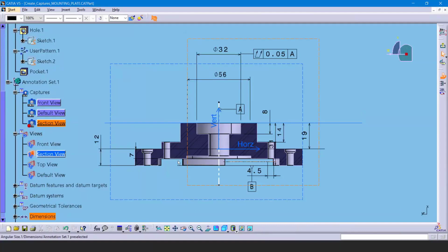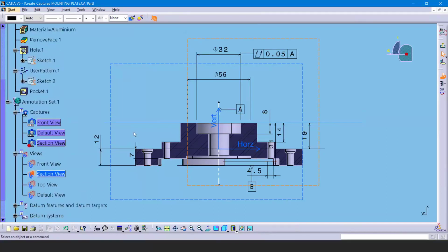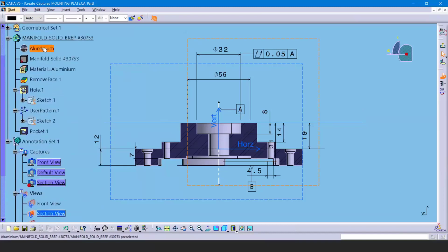So immediately you can see how that color is adjusted, and because it turned to such a dark color, I can't see the black parallel hatching lines very clearly anymore. So now the second option is that you can also change the physical pattern. You can have it be hatching lines, dots. You can also physically just import an image, which is kind of cool. And you're going to do all of that actually inside of the material itself.